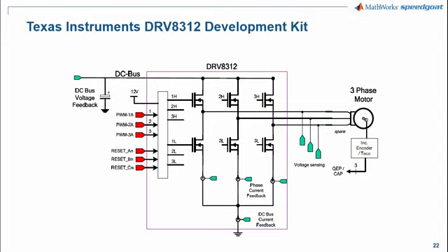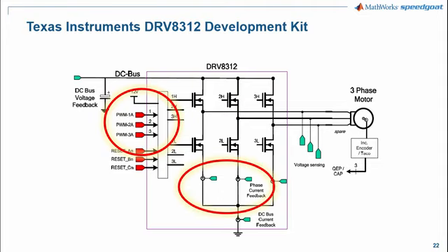Here's a simple view into our power electronics. Our controller will be varying the voltage across 3 motor phases using PWM techniques. Our real-time target computer will provide these 3 PWM signals to drive each of the 3 half bridges on the driver chip. For feedback, the TI board provides current sensing circuitry for us to acquire our current measurements. We also use an optical encoder to determine the motor position and velocity.